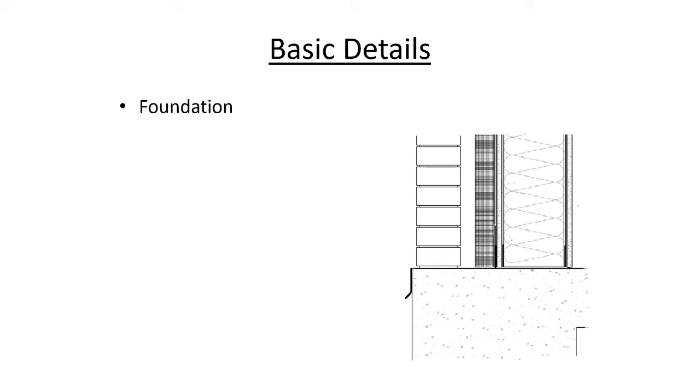The WRB comes down over the face of the flashing that we see coming out, to make sure that we have adequate draining on the exterior side of the extruded insulation, as well as for any water that might get in a liquid state through the extruded insulation to the backside, protecting the water-sensitive materials such as the gyp sheathing.